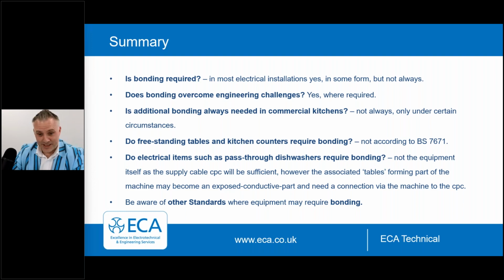Do freestanding kitchen counters require bonding? Not according to BS 7671. And what about when we talk about pass-through dishwashers and other equipment? The equipment itself should be fine through the cable CPC. However, you need to have knowledge of the tables and other elements forming part of that system if they're connected to the CPC. And be aware of other standards. So we're not always working in kitchens. We could be working, for example, in telecoms. So telecoms may have other standards, aerial systems, etc. So when you're working in different environments, there might be other British standards that you need to look at too for earthing and bonding requirements.